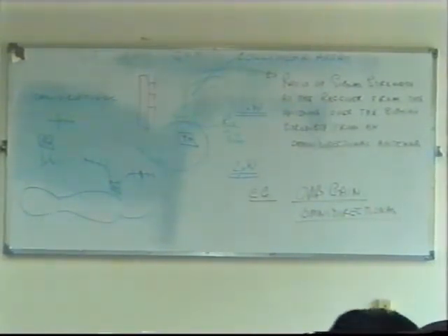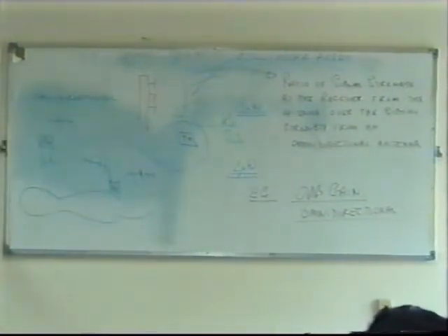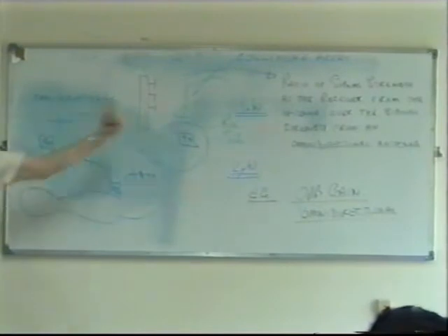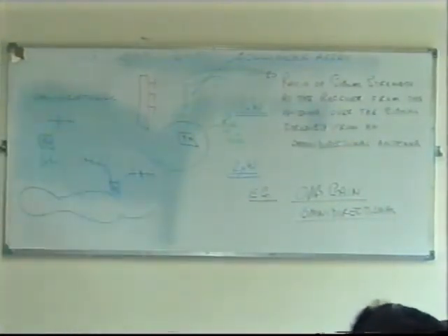But what I'm saying is, when we talk about the gain of an antenna, you can achieve the same thing: keep the transmitter power the same and double the gain of your antenna. That will also double the power at your receiver. And the range, will it be different? No. The range is a different calculation. Signal to noise ratio might change, but range no. The coverage depends on what frequencies you use, whether you use VHF or UHF. It does affect it, yes.